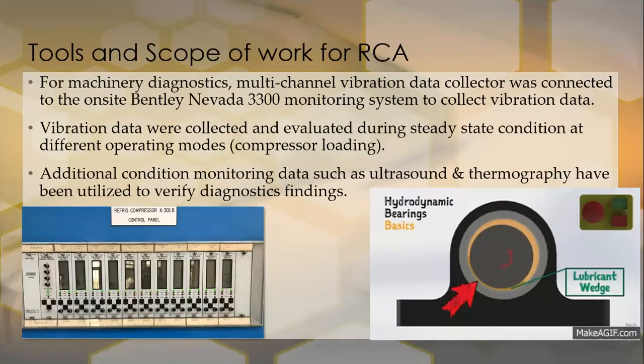To start our analysis in this system, we decided to use machinery diagnostics via vibration, ultrasound, and thermography. For machinery diagnostics, a multi-channel vibration data collector was connected to the on-site Bentley Nevada 3300 monitoring system to collect the vibration data.